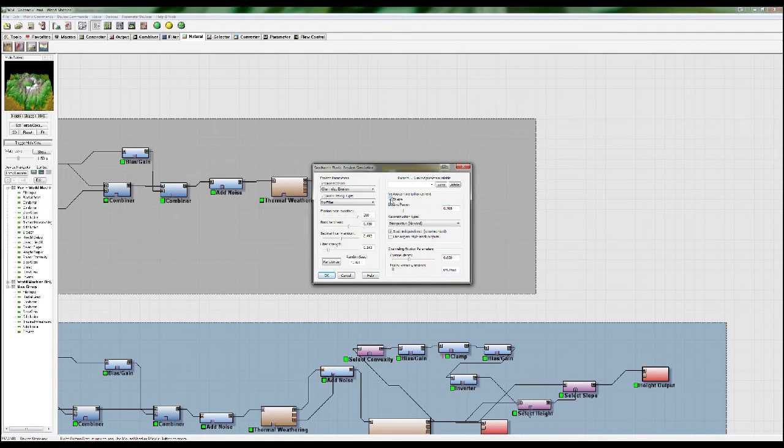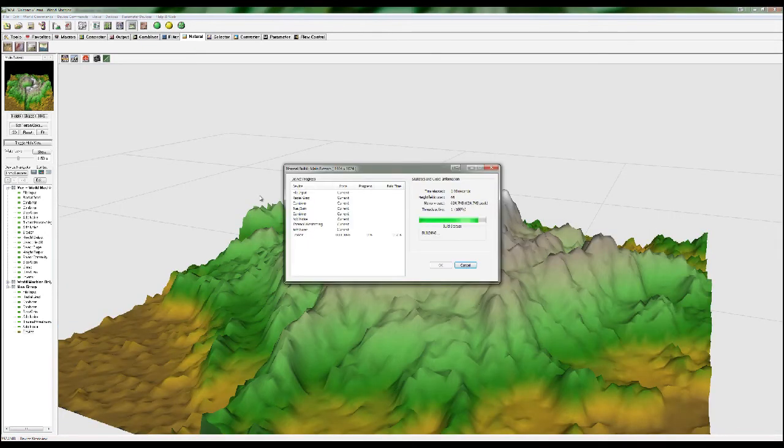And the geological time enhancement is like a multiplier. It runs the algorithm over 10 times, or just a long period. So that can be a good one if you're not happy with the amount of erosion here. This will pretty much just multiply it. So I'm just tweaking these values. When I'm moving these, I'm actually looking up in the top left here to see what the effect is. So channel depth is only enabled because we're using channeled erosion, and what I generally say is don't just crank this to the top, because it's not going to look any more realistic. Leave it generally in the middle, and always use a tiny bit of post-channel erosion. At the very least, use 5%. Basically, that means it'll carve the channel, and then it'll erode within that channel again to add a bit more realism to that.